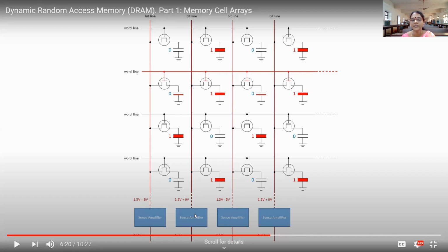So here, the sense amplifier is such a device which differentiates such a small variation in the bit line. Okay, however small the variation, this sense amplifier, which consists of flip-flops inside, identifies even this small difference. Are you following? It identifies whether it became plus or minus, and makes the value inside this flip-flop, I mean inside the sense amplifier, there are flip-flops, and makes the flip-flops either set or reset depending upon this voltage.